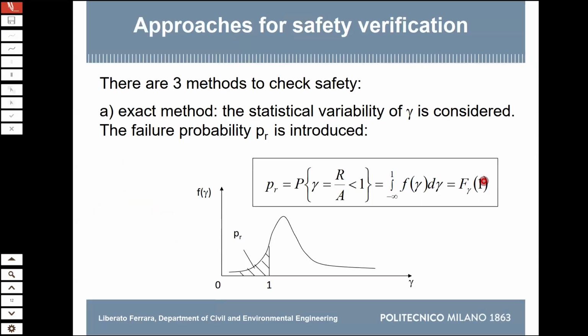But so, if we want to apply these statistics to our safety check of a structure, what shall we do? Well, in an abstract world, if you talk to a mathematician, he will say, okay, you have your resistance, you have your action. Imagine that you have a population of data for both resistance and action. And you have some kind of criterion to match them one-to-one. Okay? So you can calculate, you have a population for the safety factor.